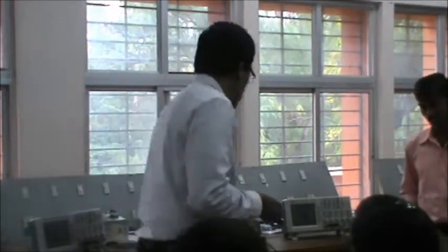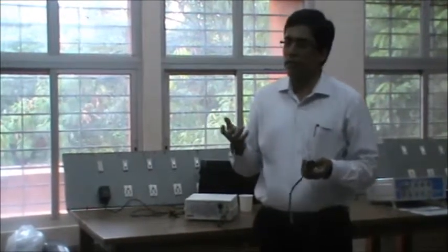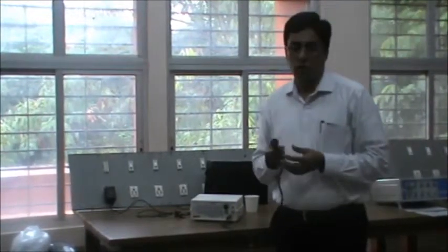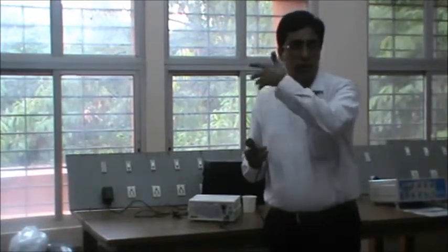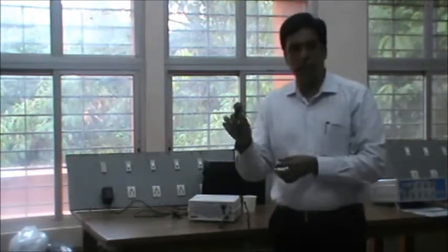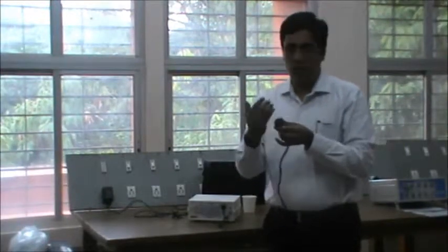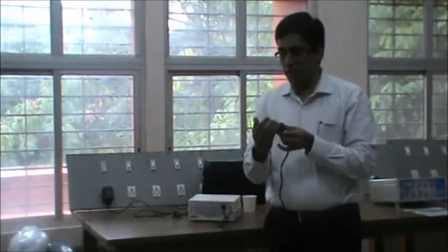Now I have another device here. Basically it starts from 2 megahertz onwards. 2 megahertz is also used as a fetal Doppler. So 2 megahertz and then you go to 5 megahertz, 8 megahertz, 10 megahertz, 12 megahertz. This is basically a piezoelectric crystal which is cut into 2 halves. One half is the transmitting side, the other half is the receiving side. Now this is generating 2 megahertz and